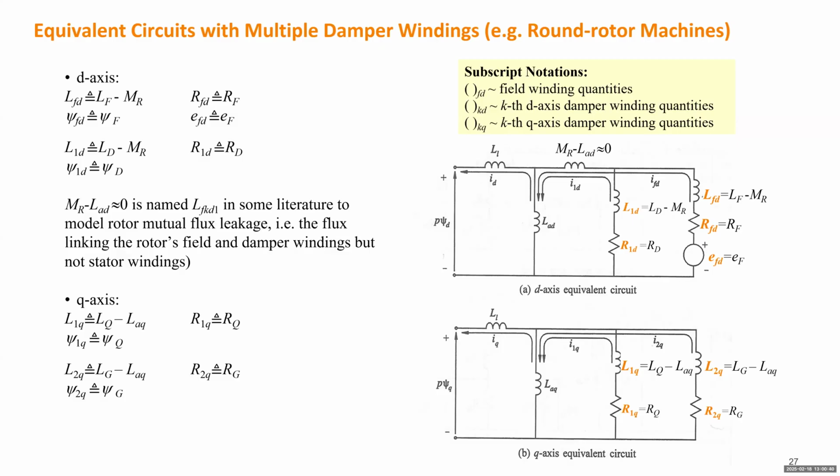This is similar to the equivalent circuit for the generator or transformer you have learned for steady state analysis. In the generator equivalent circuit, you have an internal source, which behaves like an EMF, electromotive force, connected to a reactance and resistance into the external system.